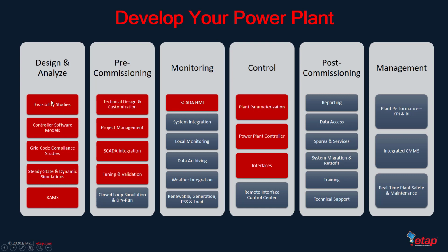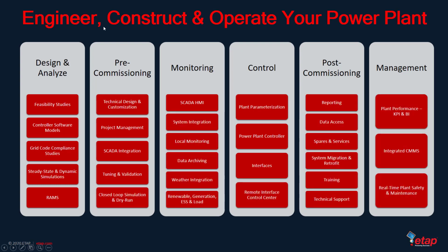Therefore, from the feasibility stages to the dynamic model design, compliance studies in steady state and dynamic, over to SCADA integration and tuning and validation of the controller, HMI design, and finally the control and parameterization of the controller is typically done as part of the development of the power plant. However, an EPC goes through all these additional stages that include the engineering, construction, and operation of the power plant.